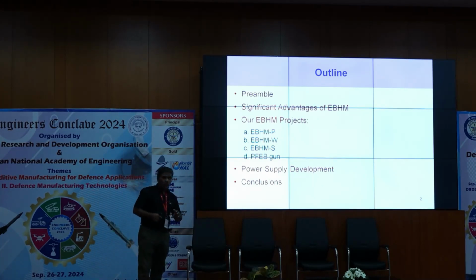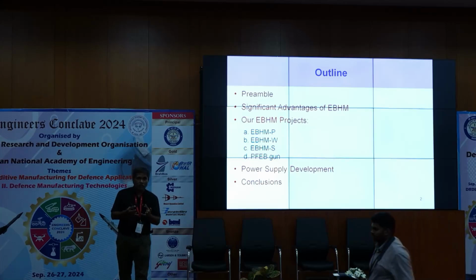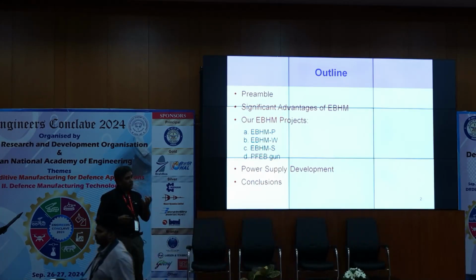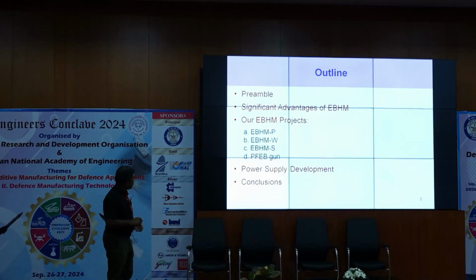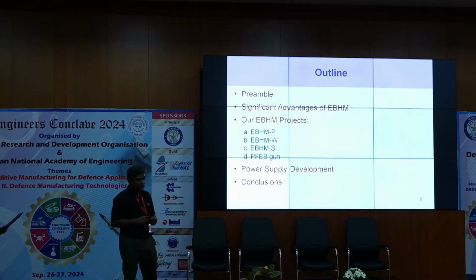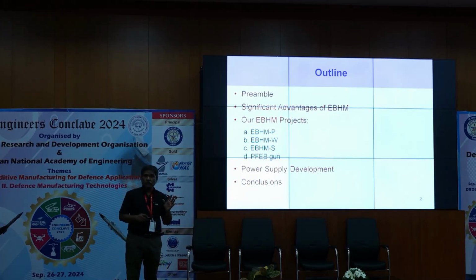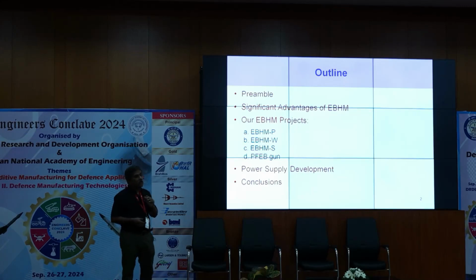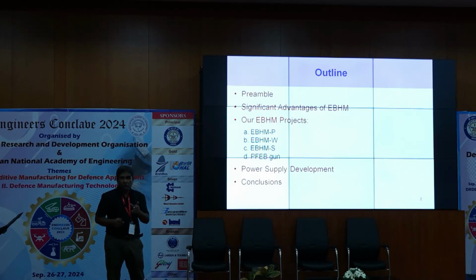So in this, we create plasma in a chamber, and then from the plasma we suck the electrons. So we have a proof of concept, but I will not dwell on that, there's no time. We have also developed our own power supply systems. These power supplies are extremely high voltage, minus 60 kV is the difference between cathode and anode. So in developing them, you also connect the filament power supply and grid power supply.